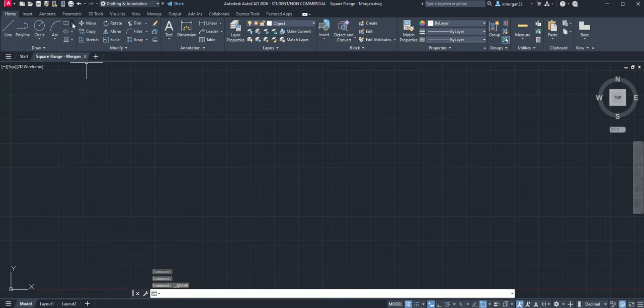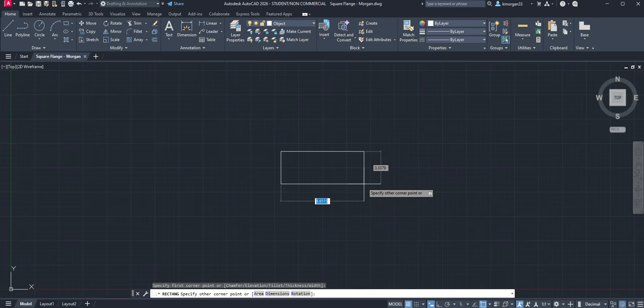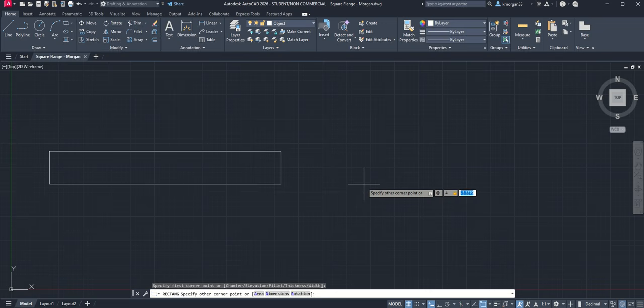What you have to do is click on this rectangle, then click on the canvas. We are going to add a mark. So you have absolute coordinates with the pound sign and relative coordinates with the at sign. Then we fill in the very first box and jump to the second box by pressing comma on the keyboard.